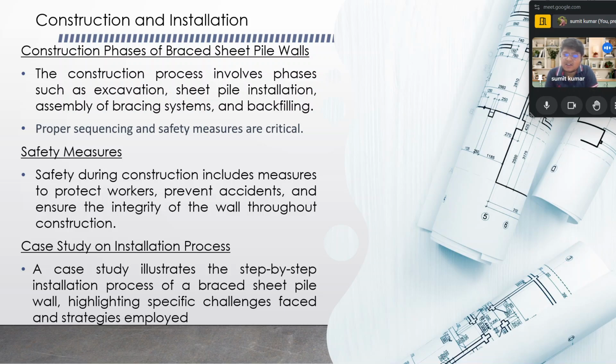First of all, we prepare the site. Afterward, the excavation takes place to insert the sheet piles. Then the sheet piles are installed at the site, and then we remove the sheet pile to make arrangement to insert the sheet pile wall. Then afterwards we do the backfilling at the specific site.